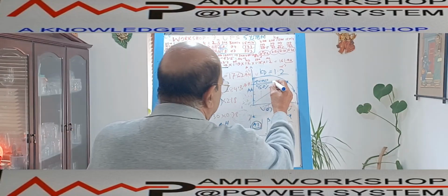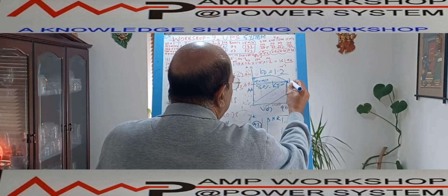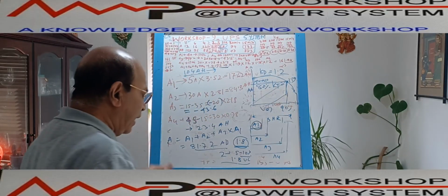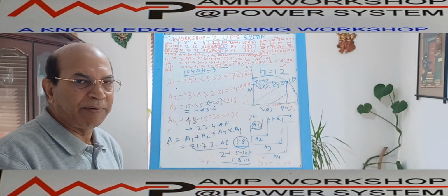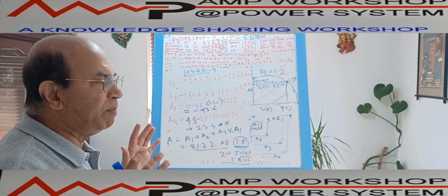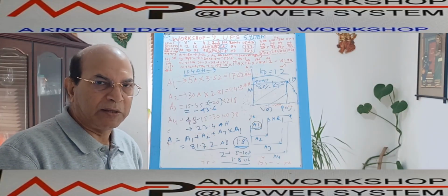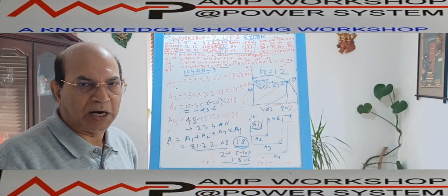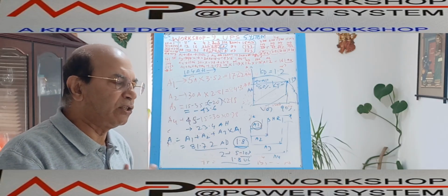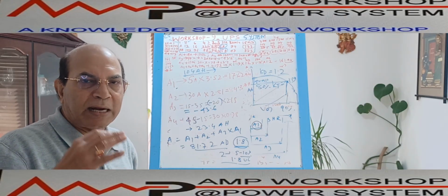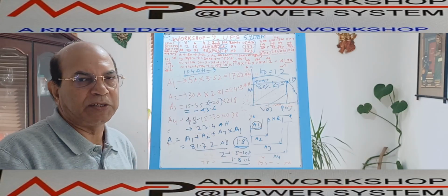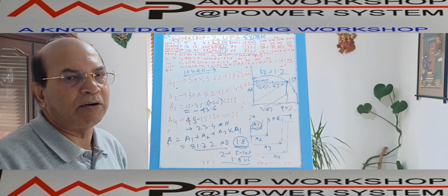So there is another factor, KT, the temperature factor, that is 1.19. Then we need to consider another factor, which we call the aging factor. What is that? The battery capacity, due to various reasons of the discharge, ambient condition, installation condition, and using condition, gradually reduces its discharge capacity. Whatever the rated capacity, it cannot deliver.